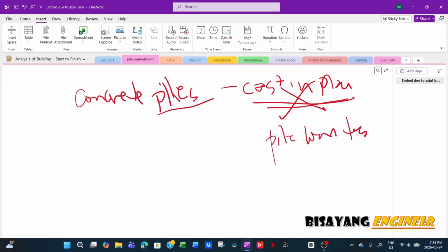That's fine if you're open to doing a pile load test, but the problem is, what if it fails? You can splice a concrete pile, but it's not really a good way to increase the capacity.